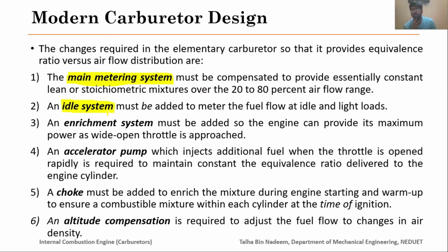Since the choke valve is only slightly open, the pressure difference between the throat and the float chamber is not enough to take the desired amount of fuel to the combustion chamber. So an additional system needs to be incorporated in the carburetor, and that system is called the idling system.